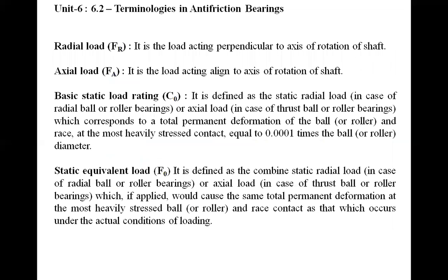Now here you can see radial load is the load acting perpendicular, and axial load is the load acting aligned with the axis of rotation. When the bearing is at a static position, it is subjected to static radial or axial load, and because of that there is a compression of the ball or roller.